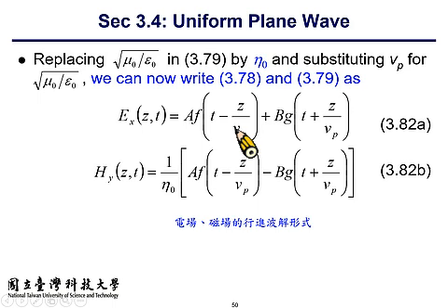So if you divide E plus, which stands for the positive Z component, by H plus, you end up with the same AF, but here comes eta, the intrinsic impedance. Again, this is the ratio of E field intensity over H field intensity. If you divide E minus over H minus, you end up with minus eta, all right?